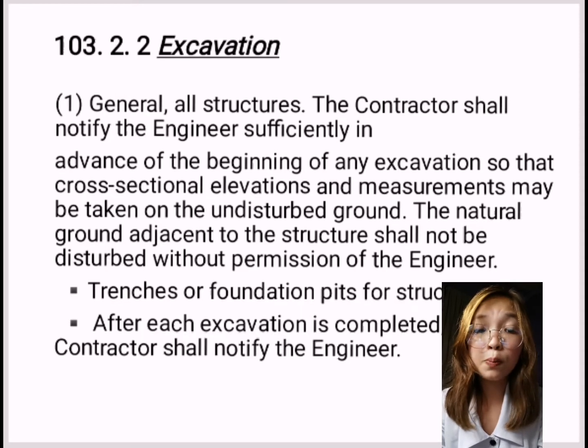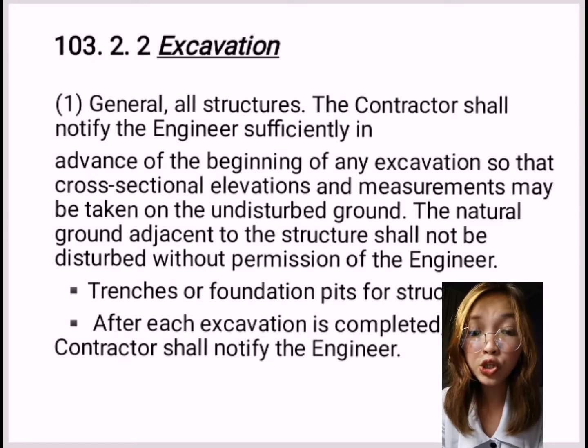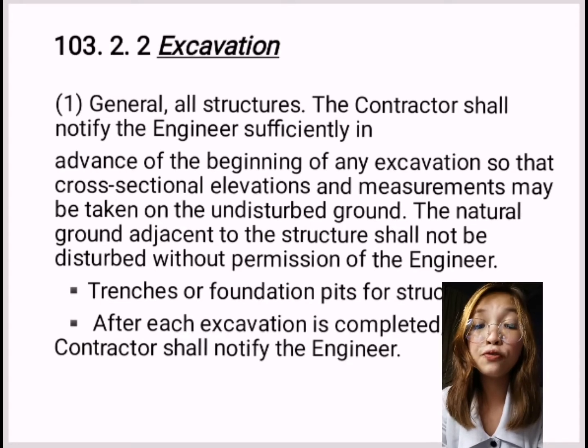The elevations of the bottom of footings as shown on the plans shall be considered as approximate only, and the engineer may order in writing such changes in dimensions or elevations of footings as may be deemed necessary to secure a satisfactory foundation. So, boulders, logs, and other objectionable material encountered in excavation shall be removed.